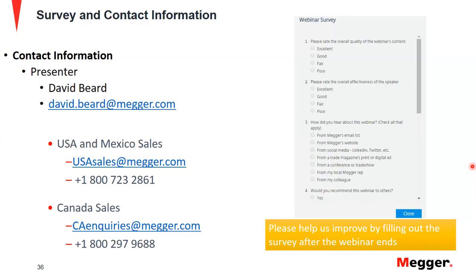Yes. In this situation, you can consider distance relays. What distance relays do is utilize the voltage and the currents to calculate the actual impedance on the line. No matter where on the line the fault is, how close to the relay it is, as long as it falls within that first zone of protection, the relay is going to trip. Coming back to the question of upstream taking longer times, the distance protection zone 1 especially will trip instantaneously, so we don't have to worry about the longer times.